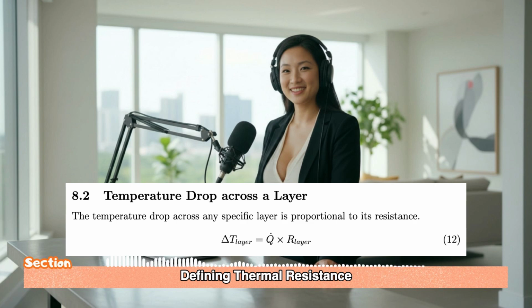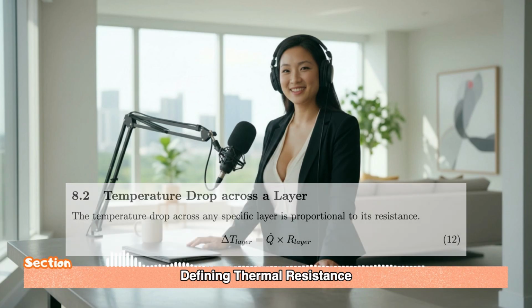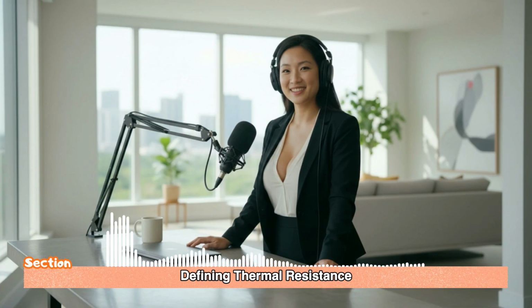I see. So the temperature drop is directly proportional to the resistance. Precisely. If you're looking at a system and you find that, say, 90% of the total temperature difference happens across just one layer, then you know that layer has 90% of the total resistance. You do. That thick layer of insulation is doing all the work, and the rest of the wall is almost irrelevant to the overall heat transfer rate. This lets an engineer spot the most effective part, or the failure point, instantly.